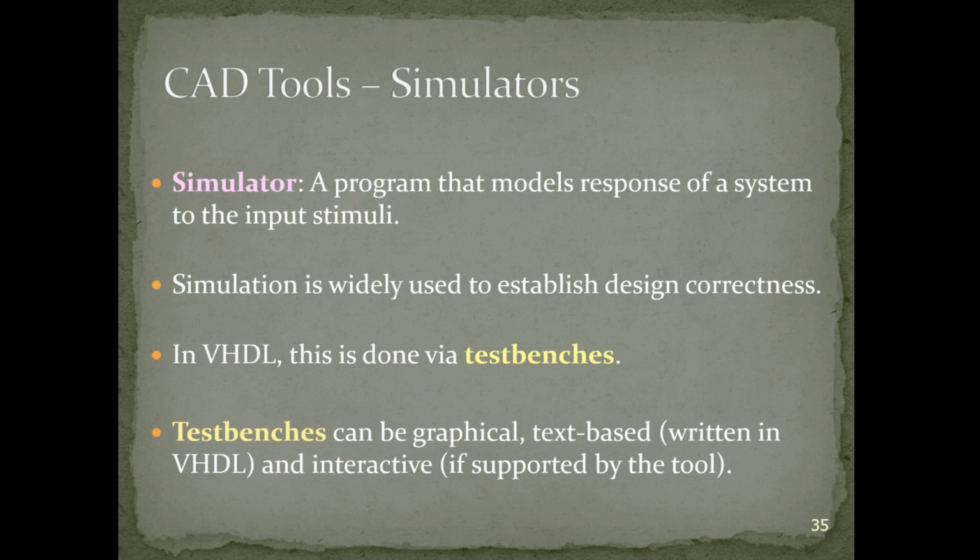So, we have various forms of entry. We put that design entry in. Next step would be to perform simulation. That is the job of the simulator. And the Xilinx tools in our case have quite a competent simulator, which basically, with the aid of a test bench, would provide the inputs that we want to use for simulation. So what the various input values would be. And then as soon as you press simulate, it will use those inputs to generate the outputs.